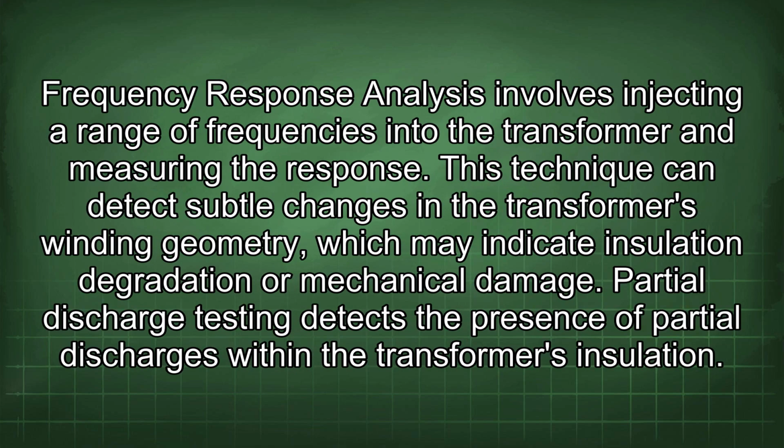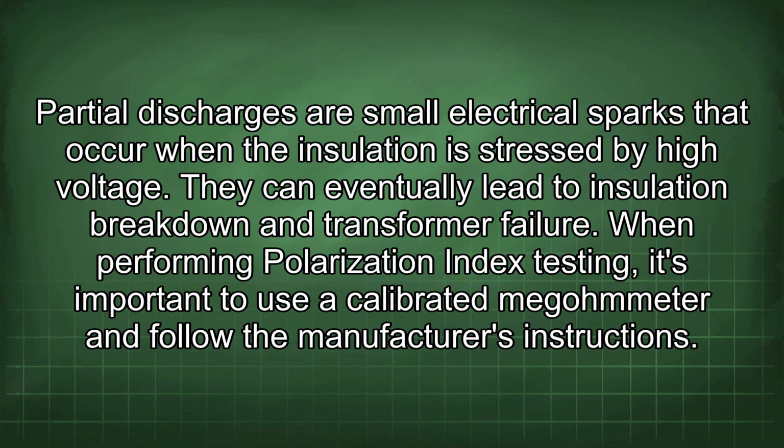Frequency response analysis involves injecting a range of frequencies into the transformer and measuring the response. This technique can detect subtle changes in the transformer's winding geometry, which may indicate insulation degradation or mechanical damage. Partial discharge testing detects the presence of partial discharges within the transformer's insulation. Partial discharges are small electrical sparks that occur when the insulation is stressed by high voltage. They can eventually lead to insulation breakdown and transformer failure.